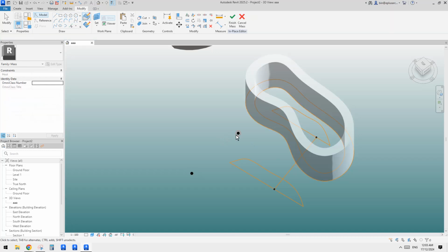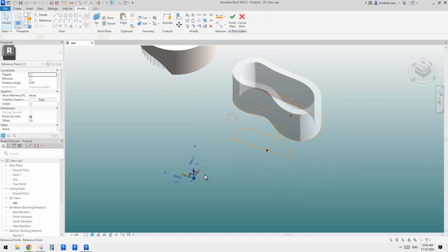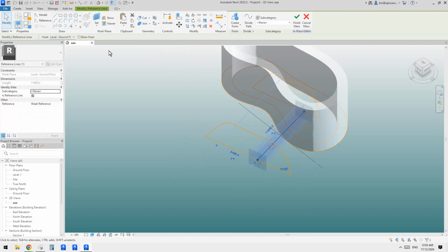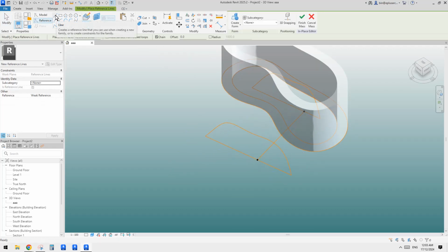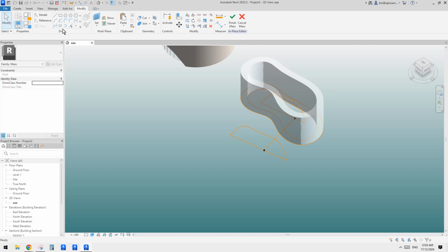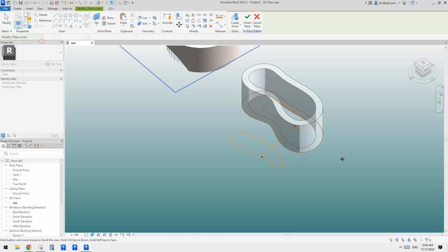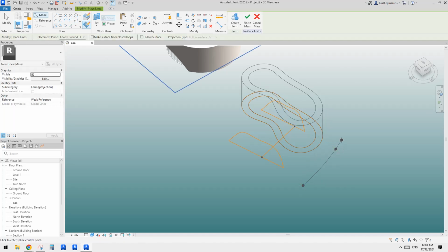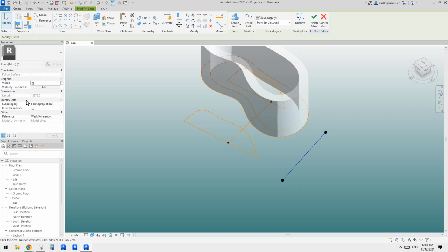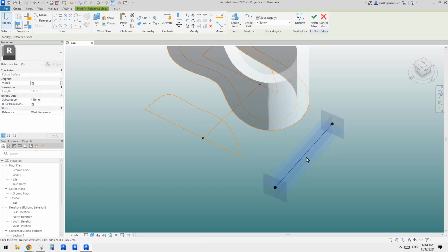If we create a spline, because when we create this one, we just use the reference line and we created a straight line, right? But if we use spline through points instead, which means we need 2 points, you can directly draw on world plane, draw onto a level, ground floor, and create a spline through points and escape. So for this reference line, we can change it to a curved line if we want to.